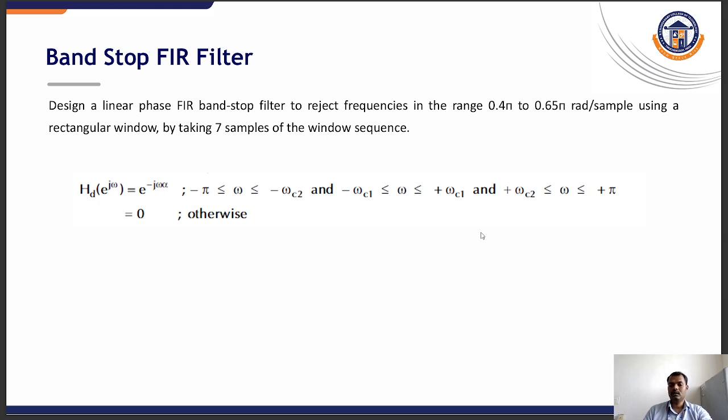The applications of FIR filters: it is used in audio signal processing, where it is used for equalization, noise reduction and crossover networks in speaker systems to ensure no phase distortion is introduced to the sound. It is also used in digital communication, in which it is employed for channel equalization and anti-aliasing to preserve the shape of data pulses and prevent inter-symbol interference.